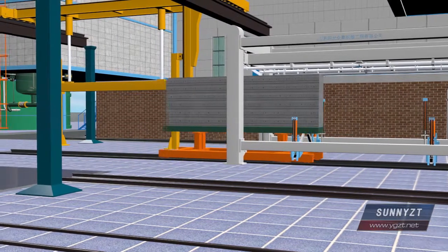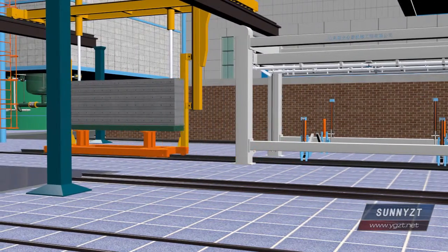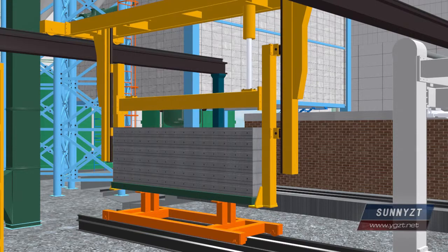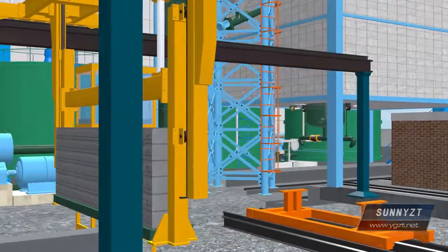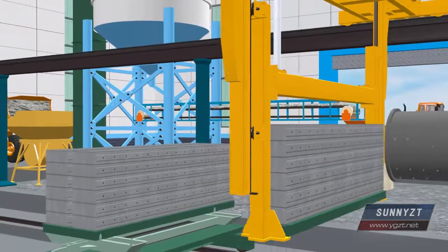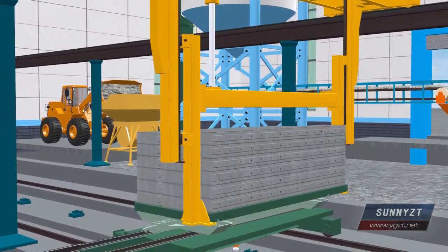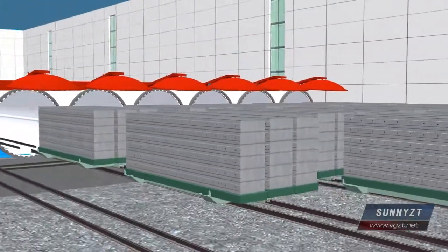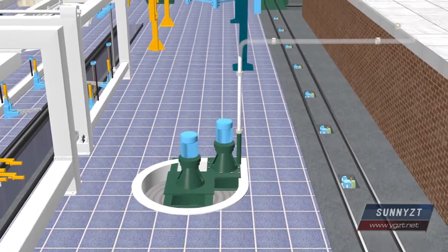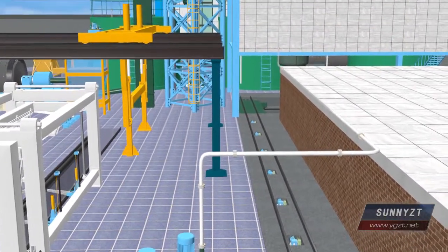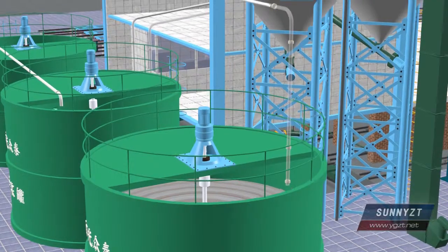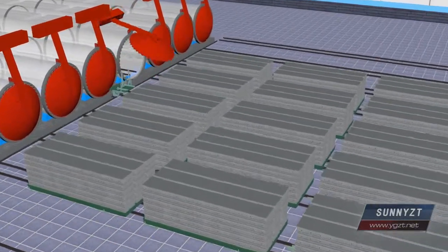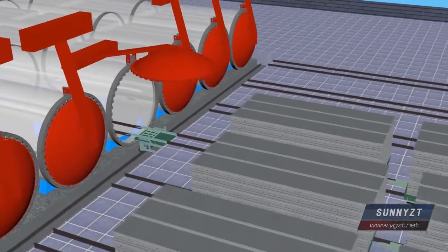Complete marshalling after the second cutting trolley moves the green body to the underneath of the marshalling crane and hoists it onto the steam curing trolley in front of the kettle. All of the wastes produced in the cutting process can be recycled. The cut green body and the side plate are placed on the steam curing trolley in order.